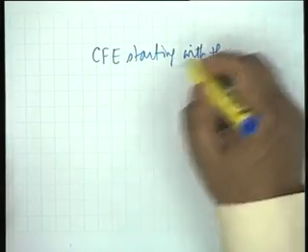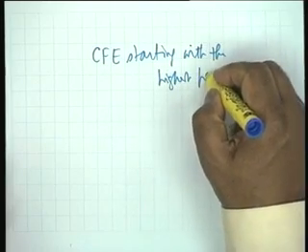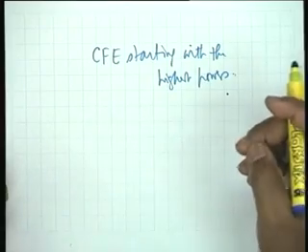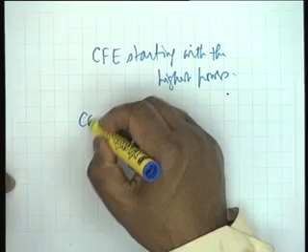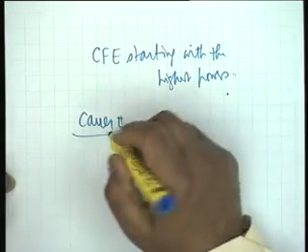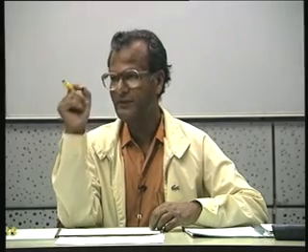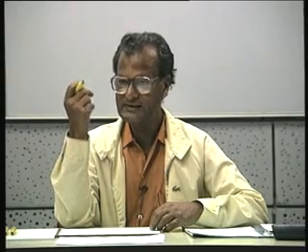Starting with the highest powers. Now, we will come to an illustration of this a little later, but in the same breath, let us discuss Cover 2. While Cover 1 focuses attention on the point at infinity, Cover 2 focuses attention on the point at the origin, that is s equal to 0, because for an LC driving point immittance, s equal to 0 is also a critical point. It is either a pole or a 0. It cannot be anything else.